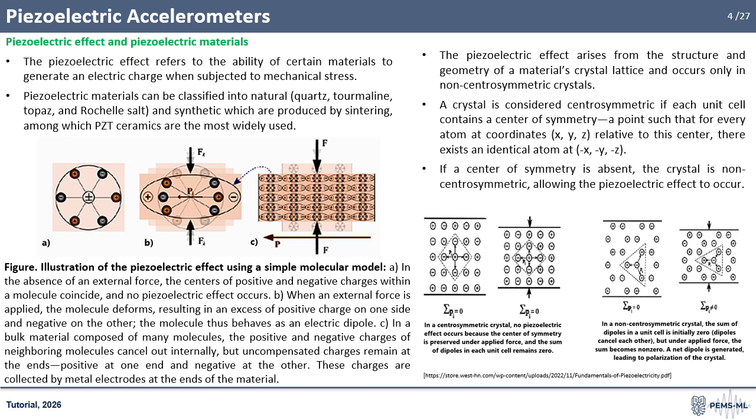The piezoelectric effect can be explained using a simple molecular model. Without an external force, the centers of positive and negative charges coincide, so no piezoelectric effect occurs. When a force is applied, the molecule deforms, separating the charges and forming an electric dipole. In a bulk material, internal charges cancel, but uncompensated charges appear at the ends of the material. These charges are collected using metal electrodes. The piezoelectric effect originates from the crystal lattice structure and occurs only in non-centrosymmetric crystals.